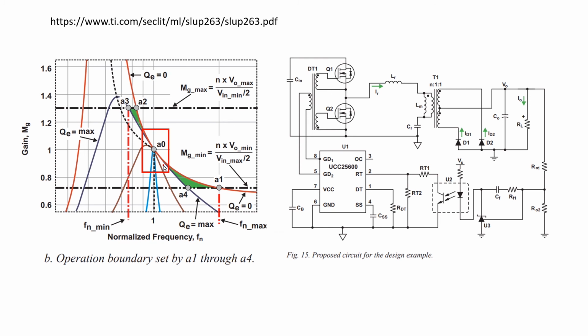Such architecture brings 2 benefits. First, due to the resonant contour we have a sine wave type of current flowing through the transformer and therefore similar output voltage. You don't need large inductivities to filter out DC voltage. Second, your gate driver all the time generates a symmetrical pulse form with 0 switching noise. As you can see, all regulation is done just by changing frequency. This is a significant benefit compared to the flyback architecture with the pulse width regulation principle.